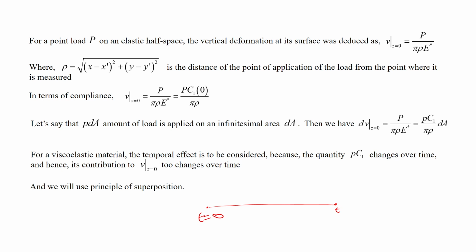The load that has been applied varies, or the compliance of this material, the creep compliance, also varies. So we need to consider the effect with respect to time. This quantity PC1 changes over time, because the pressure can change over time, and C1, the compliance, also changes. Therefore, the contribution to V at z equal to 0 also changes over time.